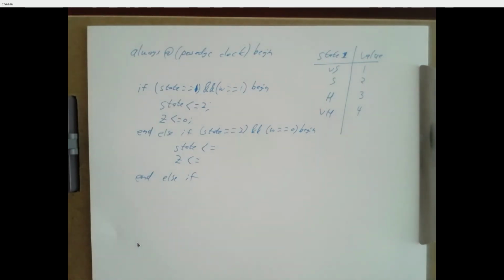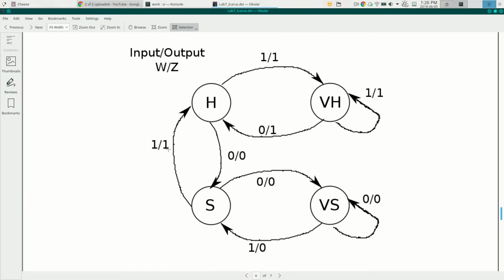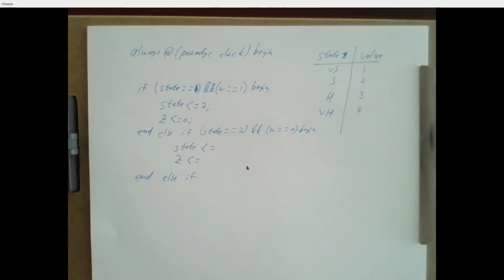So we can skip the whole state transition table, the whole setting up with the flip-flop inputs, the equations, the K-maps, all of that, and really just describe almost in words what we want the machine to do based on that state diagram. Now it's a bunch of if statements. It's going to be at worst case 8 if statements. Some of them we don't care about. Those 2 on the end, right, we never actually change state, so we don't really care about these cases. But if you're in this state and your input's a 0, then we want to go to this state and set your output to a 0, and so on. And you write that code, and there's your Verilog module for the state machine.